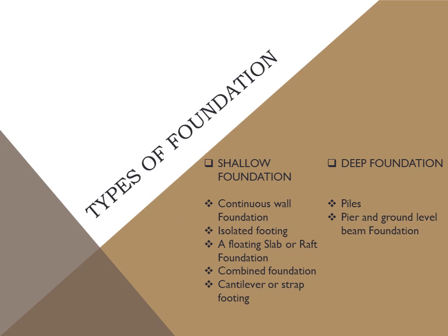Under shallow foundation we have continuous wall foundation, isolated footing, floating slab or raft foundation, combined foundation, and cantilever or strap foundation. Under deep foundation we have piles, pier, and ground level beam foundation.